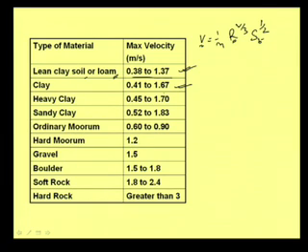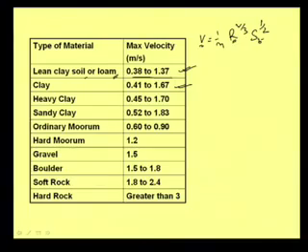So this range is still quite large, and experience counts at that point. Looking into the situation, we should know what can be the value. In fact, sometimes we may have to go for experimentation also to know the exact value. But for the design of a small channel section, we may take this value and go by this permissible value. When we are not sure about what the maximum value will be, we should go for the minimum value suggested as the maximum velocity, because the range can be from 0.41 to 1.67 for clay, say. So if it is clay and we do not have much idea, we should be conservative in our design and use 0.41 meter per second as the value, because if we take the higher value, we may not be sure that at lower than that also the clay surface can get eroded.